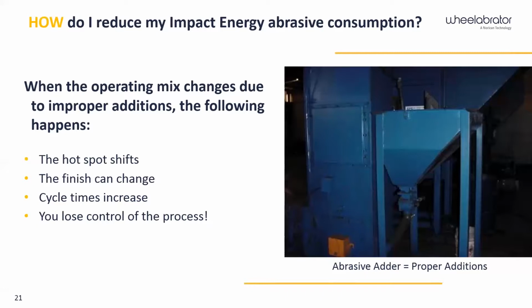I've had guys who run these abrasive additives tell me, man, the problem is that thing doesn't stay open. My valve only stays open for 5 seconds and then it closes. So they want to go down there and switch the air line so it stays open the whole time. Well, that's the opposite of what you want, because again, all you're doing is slugging your system. You want it to intermittently open and close to keep that good operating mix going.